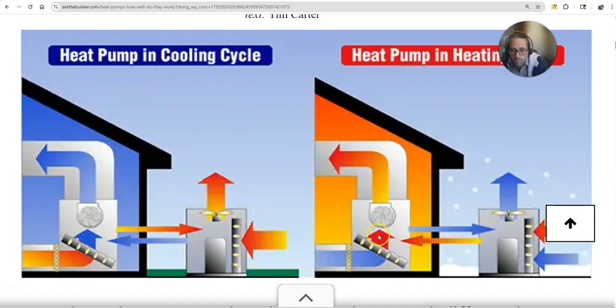With a heat pump, there's something called a reversing valve that turns the evaporator, which is the thing inside. This is your evaporator because it evaporates, and your condenser's outside. In heating mode, the outside coils actually turn into an evaporator because they're the same coils. It's just the temperature that changes. So this turns into your evaporator outside. It evaporates, pulls heat from outside, takes that heat, condenses that refrigerant, and dumps the heat back out, and that sends it up into your ductwork and so forth.